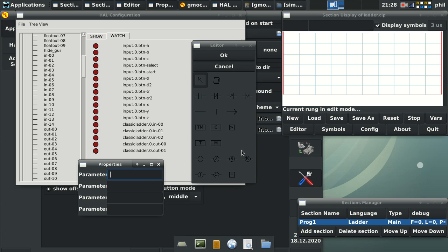output. If you watch the tutorials on YouTube, there is a guy that is adamant that there is a huge difference between normal open input, normal closed input, and normal open switches and normal closed switches. In PLC logic, they're not actually called normal open and normal closed. They're called make coils and break coils. And when you watch the instructional videos, you will soon see that a make coil and a break coil do not care if you're using a normally opened switch or normally closed switch. All it cares about is digital input 0 and 1.